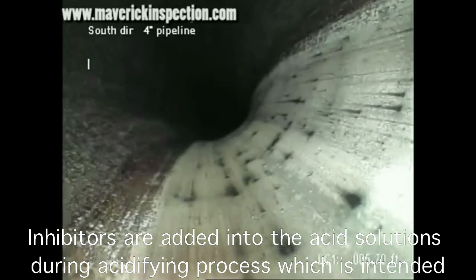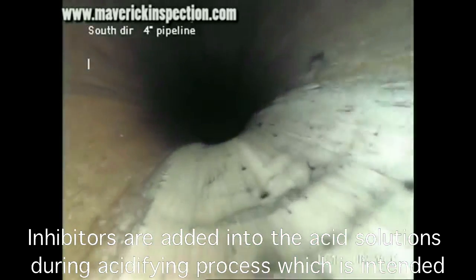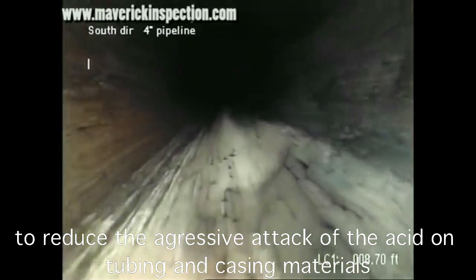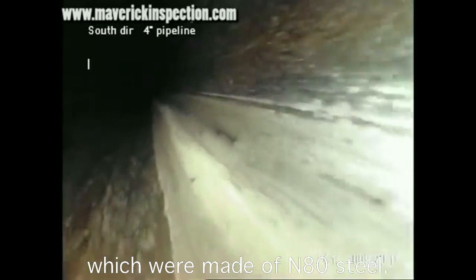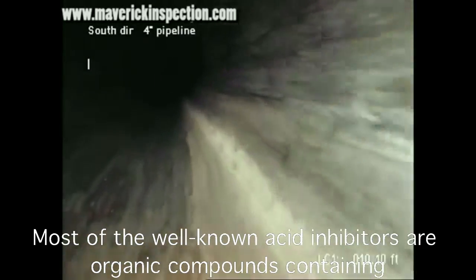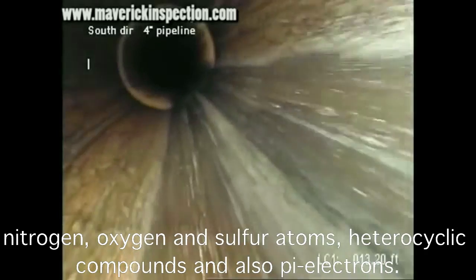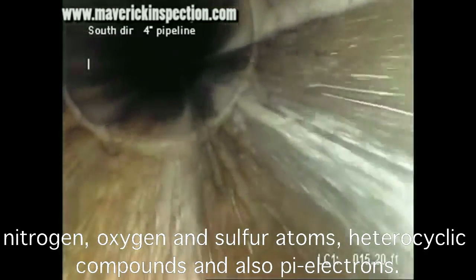Inhibitors are added into the acid solutions during the acidizing process, which is intended to reduce the aggressive attack of the acid on tubing and casing materials, which were made of N80 steel. Most of the well-known acid inhibitors are organic compounds containing nitrogen, oxygen, and sulfur atoms, heterocyclic compounds, and also pi electrons.